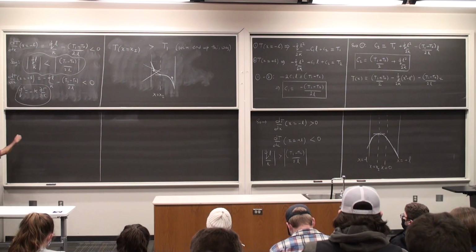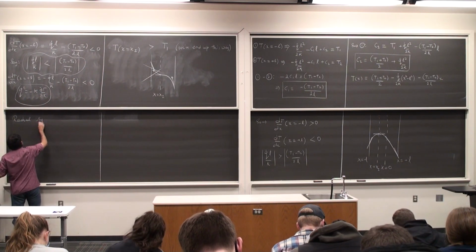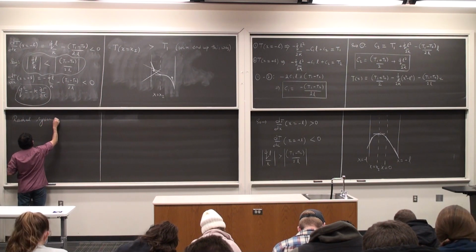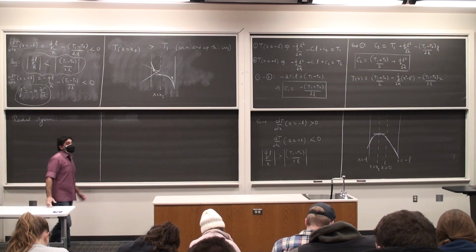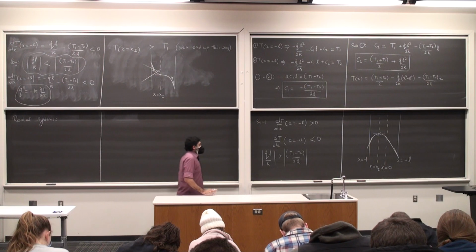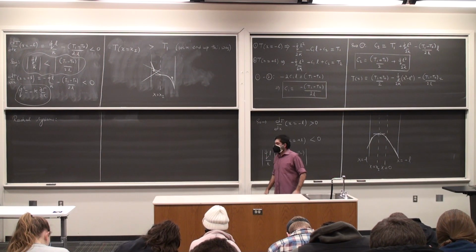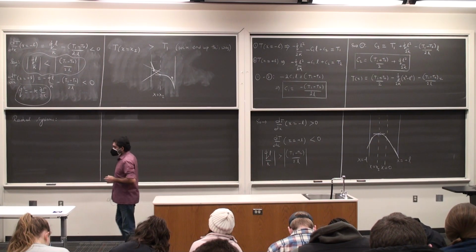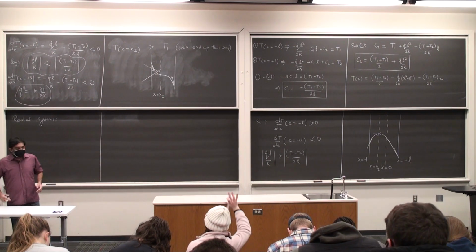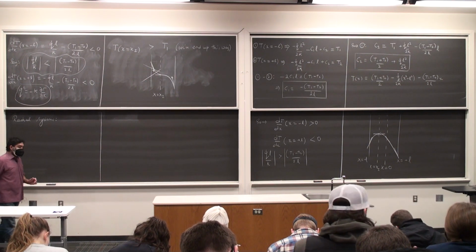All right, so radial systems. Heat transfer in radial systems. So this could either be cylindrical geometry or spherical geometry. Cylindrical geometry is, as an engineer, more fascinating because of all these pipes that are carrying heat or cold fluid from one region to the other. You can have pipes inside reactors and so on, which are also going to be doing something similar.